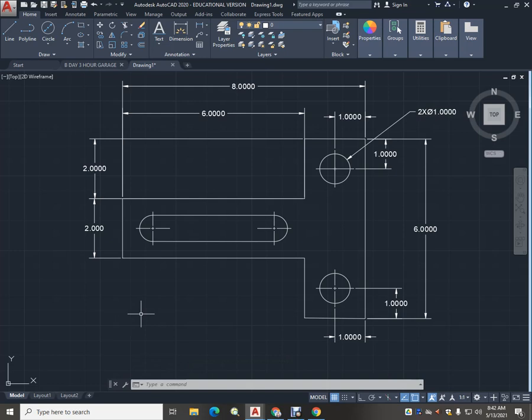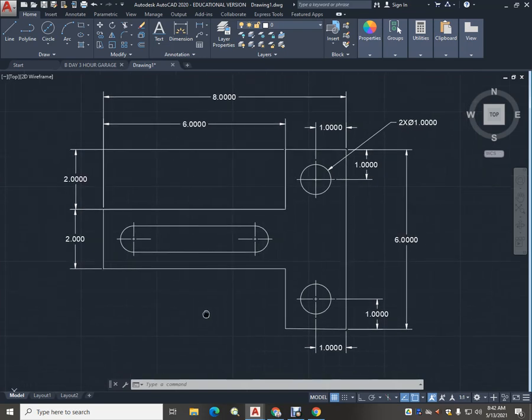So that's, you know, when you start doing consecutive dimensions, it is a little bit better, and it makes the machinist a little more comfortable rather than having tried to do the 2, a 2, and 2, and then still maintain your 6th dimension. Because if this needed to fit into a holder, we'd have a difficulty trying to maintain all 3 dimensions and then try to hit your 6.